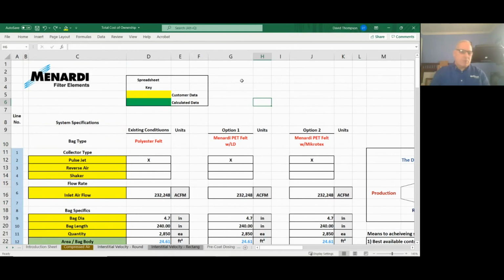That's what you do. So we offer things like tube sheet plugs, so you can pull bags out and plug holes in tube sheets. We don't recommend pulling out that many bags because it's very difficult, but sometimes it doesn't take that much to alleviate. I shouldn't say alleviate the problem, but you can make the problem less of an issue. If you had to remove some bags, that's probably one of the only ways. And again, you're compromising by taking away filter area, shortening bags, and so forth.